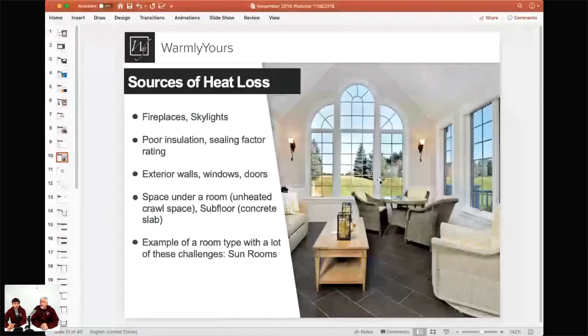Right. Okay. Let's say that in this room, there's a kitchen down below this floor. Or that there is an unheated crawl space under this floor. Which room would feel warmer with the same number of BTUs? Heated kitchen would be definitely better. Okay. One last example. A person with a room like this probably has at least 3 exterior walls, right? We just don't see the other 2. Yeah. Let's say that we move this to a bathroom on the 2nd floor. This bathroom has 0 exterior walls. Would that room be warmer than a bathroom situated like this that has a bunch of windows, that has 3 exterior walls? Yeah, you take those 3 exterior walls out, you're killing those 3 monsters right there.